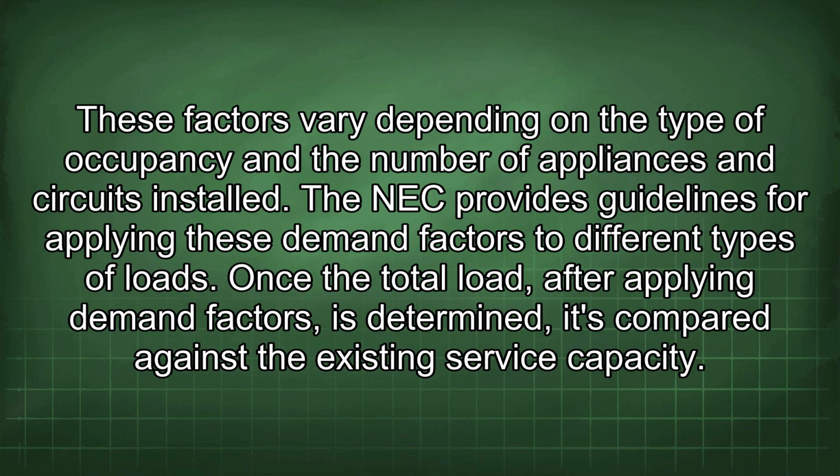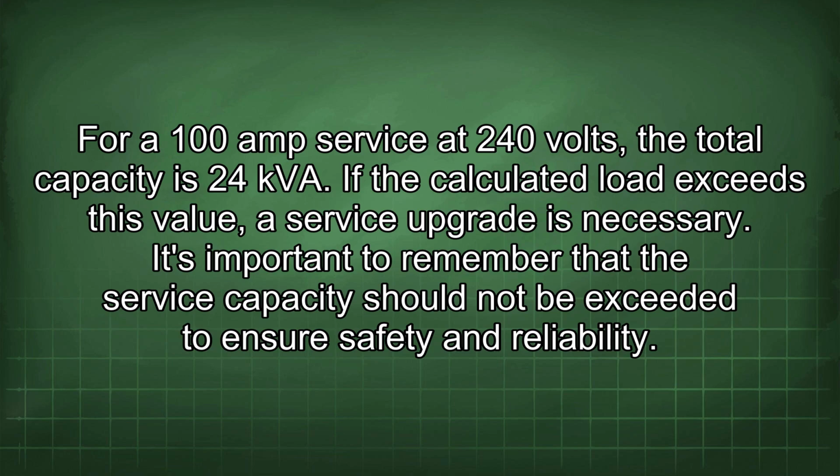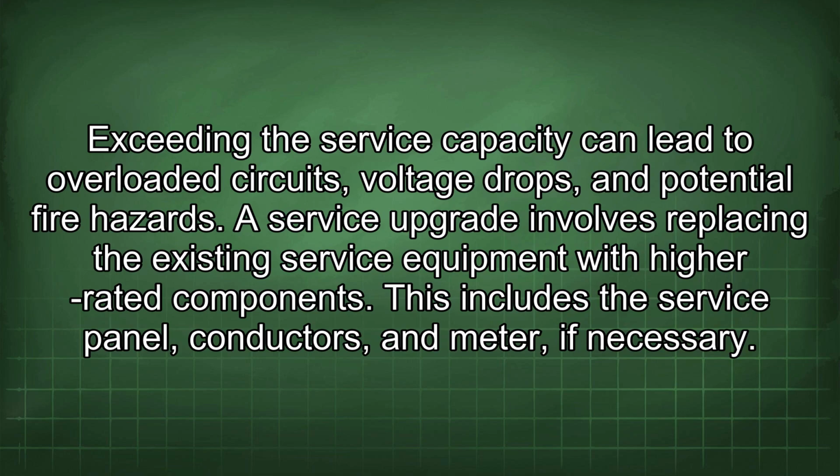Once the total load, after applying demand factors, is determined, it's compared against the existing service capacity. For 100 amp service at 240 volts, the total capacity is 24 kVA. If the calculated load exceeds this value, a service upgrade is necessary. It's important to remember that the service capacity should not be exceeded to ensure safety and reliability. Exceeding the service capacity can lead to overloaded circuits, voltage drops, and potential fire hazards.